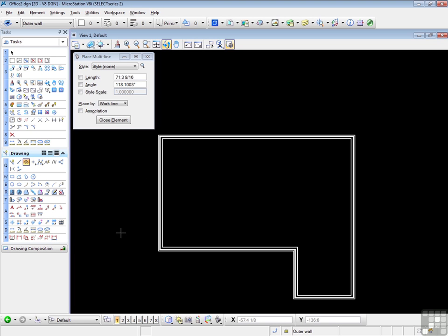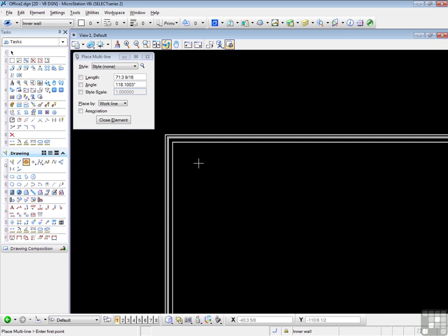And we can draw our interior walls. Make sure the tool's running. We're working by the work line. We need to change the level to inner wall. Let's start at this top corner here. We are going to place the compass at the outer block wall junction. So we need to F11 and O, place the compass, drag in this direction, and we need 20 feet. There's 20, there's my junction, left click, and we drag.